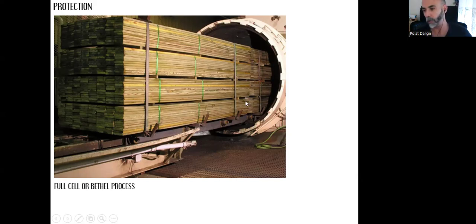Since they are full now, there won't be any water exchange or humidity exchange, and based on the properties of that chemical substance, we can repel insects, or we can extend the burning time. And in Turkish, that's what we call emprenye. It's a French word, obviously, same as impregnation in English. That's what we are doing. We are impregnating those chemical substances inside these timber voids.